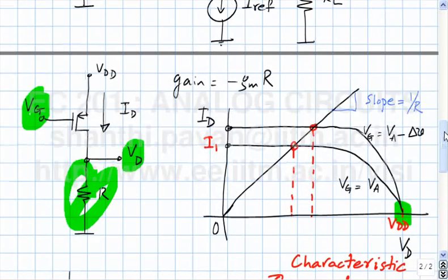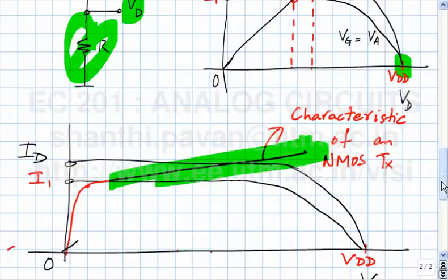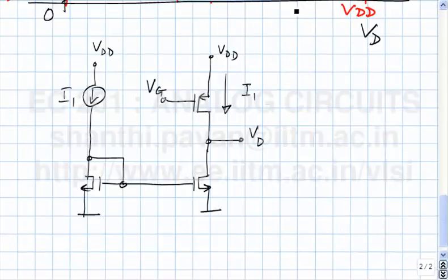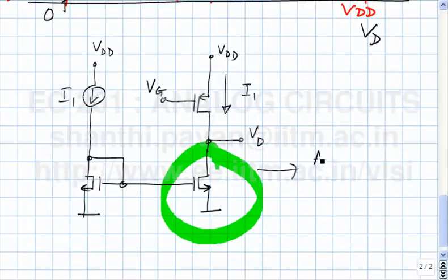It turns out that, though this is not a fundamental thing, on an IC making large resistors is difficult. And if you wanted to get a large gain, you needed a large resistor, so that resistor would occupy a lot of space. And not only that, you also need a large power supply voltage which would drain off your battery very quickly. So this is called the active load.